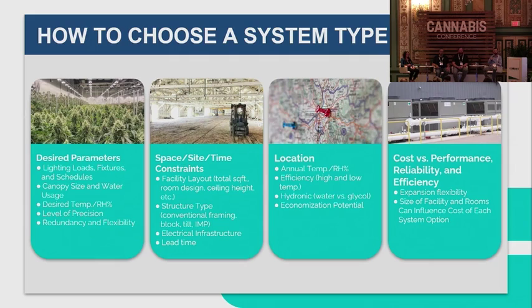That opens up a whole other world. Past that, geographic location, and your timeline. Supply chain and timeline can be one of the biggest deciding factors. I've built facilities out where the intention was a chilled water system, but they had to be operational in 120 days. And a couple hundred tons of chilled water is not something that can be engineered and produced generally in